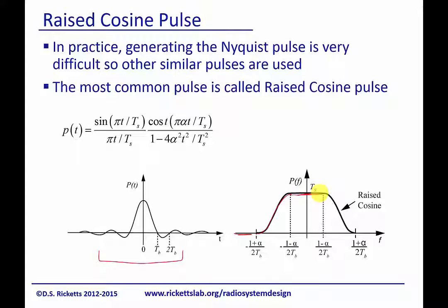And these are done digitally, so there's some digital signal processing that figures out how to shape this in the frequency domain. And the bandwidth, because this is an artificially designed filter, is the distance between these two edges, because it really is 0 out here and 0 out here theoretically. So the bandwidth is simply 1 plus alpha over TB.